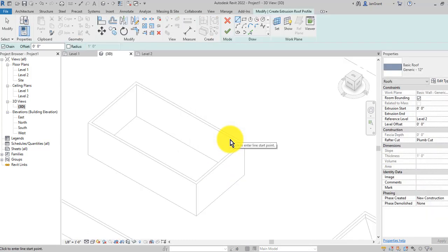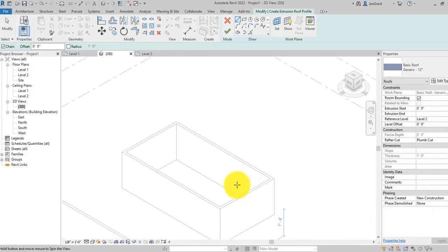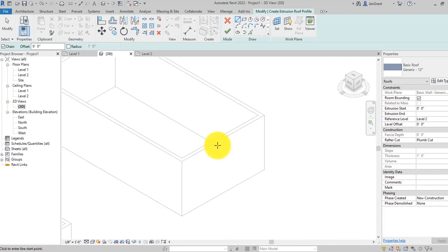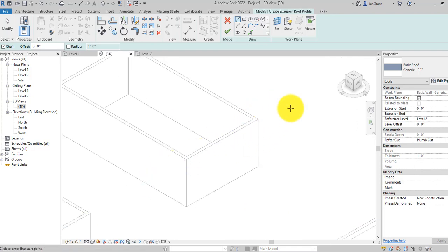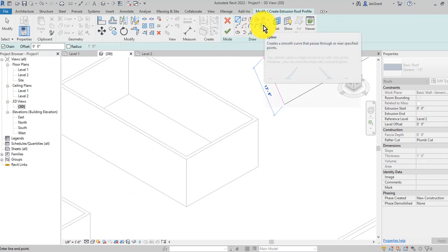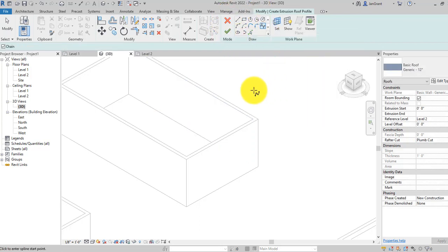So it doesn't look like it, but we're in the sketch mode, and whatever we draw is going to be drawn on this edge. So at this point, I have free reign. Just to line it up, I'm going to extend from this corner and click. And then instead of using straight lines, I'm going to get a little curvy here and create maybe a spline. There's a spline under the draw tools.